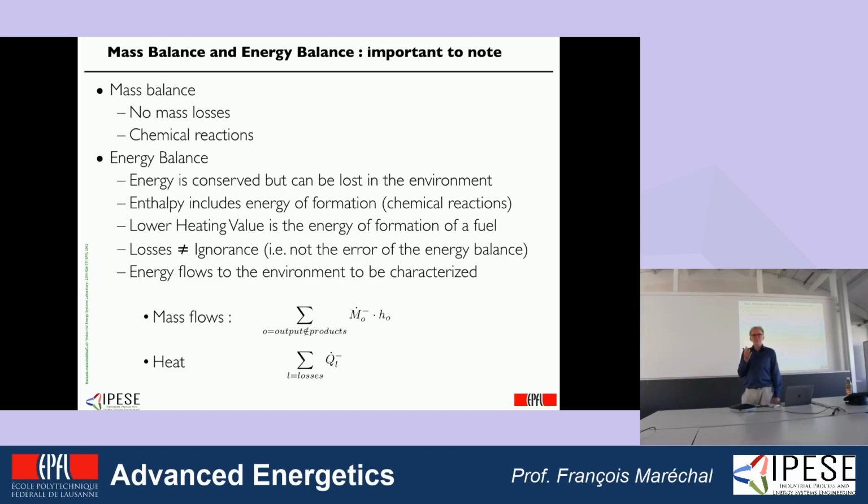When you draw the energy balance, you do not have to forget about the enthalpy of formation. So if you have chemical reactions, and combustion is a chemical reaction, adsorption is a chemical reaction, you have to account for the energy of the reaction. Otherwise, you will lose information.